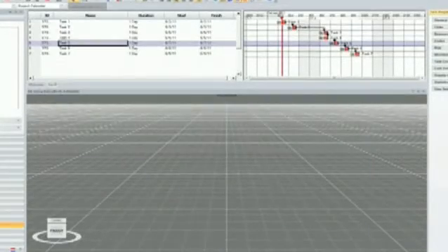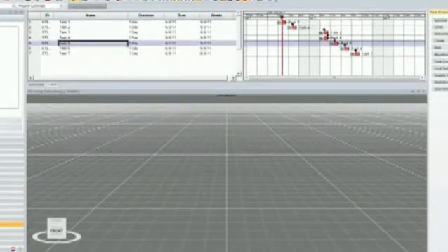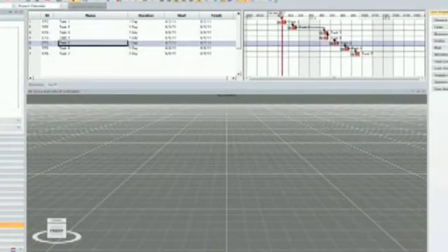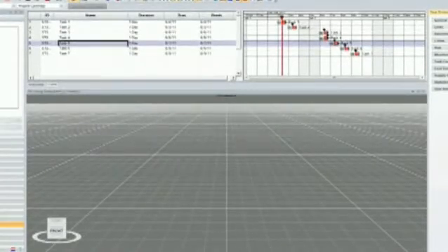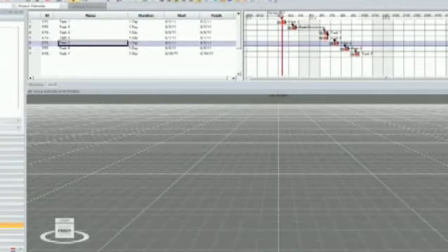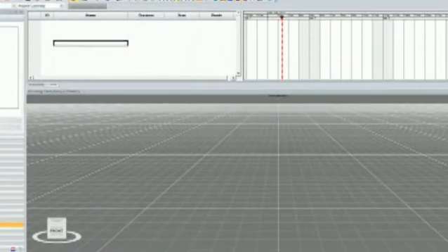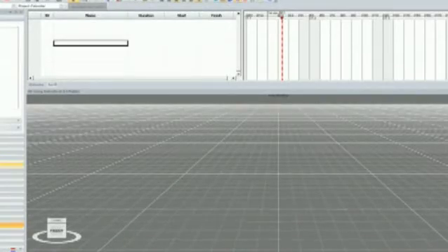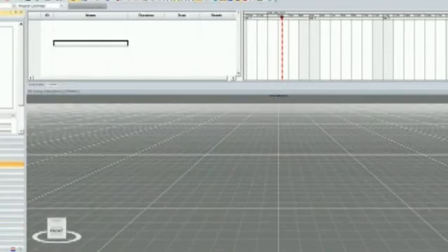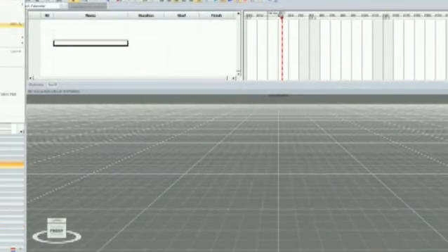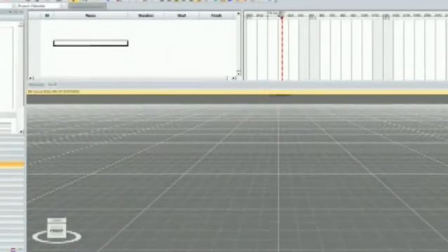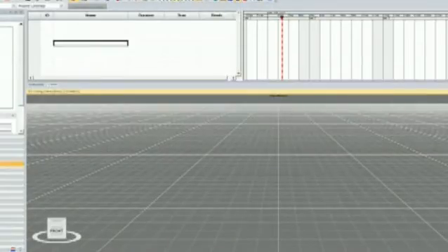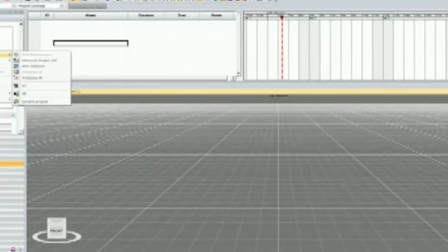Now, with that said, if we're good, I'm going to jump in to bring a model in, bring a schedule in, and link it and show you how we link the model to the schedule. Is that good? Yeah. Okay. So let me just back up and I'll take all this stuff out and get a fresh sheet. Okay, so I'm going to go to my external data tab, and I can also go file, import, but I like to use my tabs over here so I see what data I have in. So external data, in this box here, I'll right click, I'm going to say import.